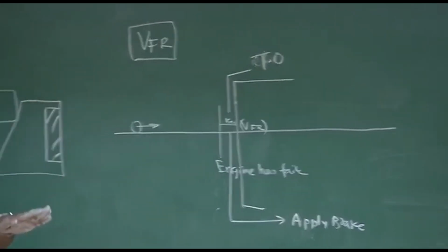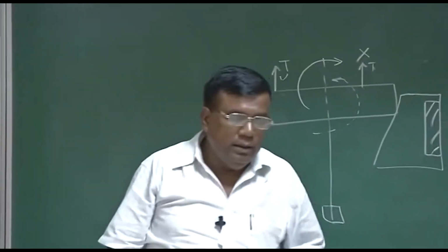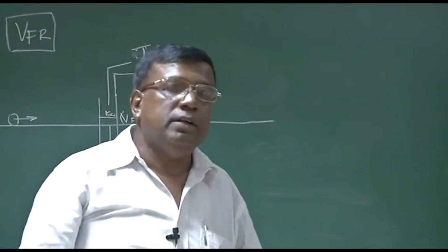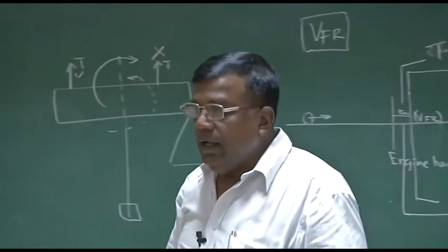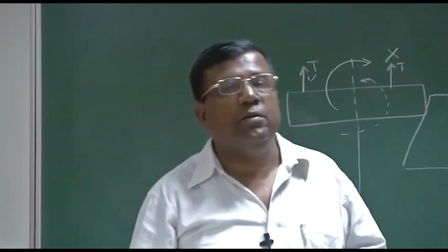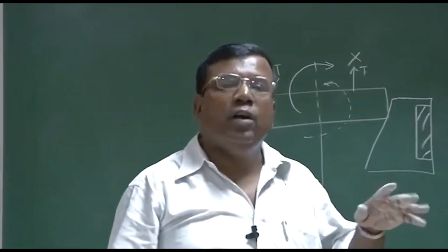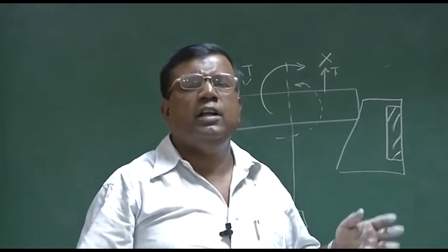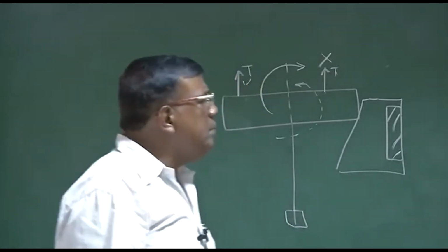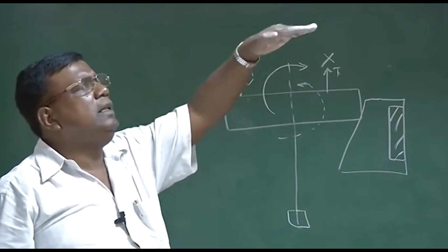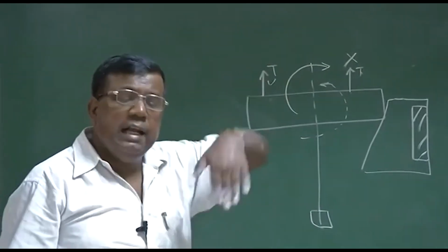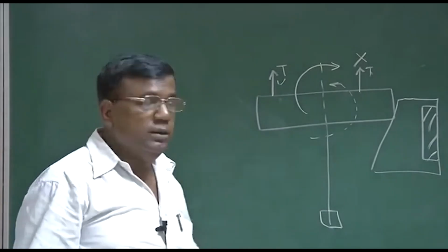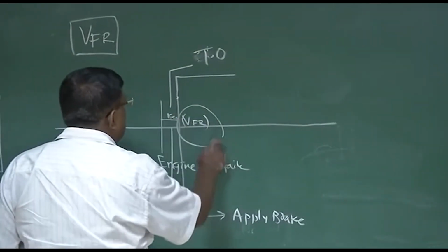When he goes for takeoff, you also have to ensure that the design is such that even after one engine has failed, the aircraft has enough excess power to climb up to a particular altitude easily, at ease. And these are as per the regulation. There are numbers for that, right? Because he should climb and then take a circuit flying, and he may land at the same airport or at a nearby airport depending upon the emergencies. Okay? So how do I select that VFR?